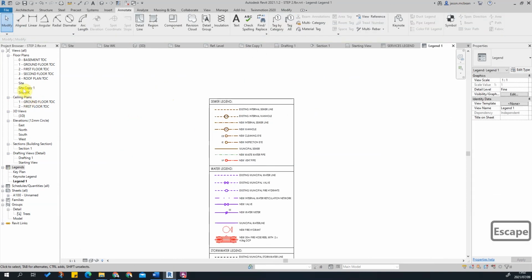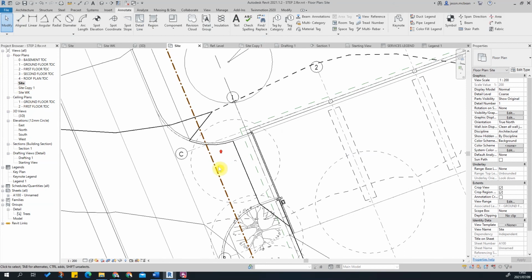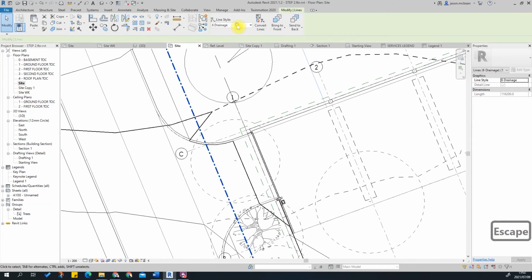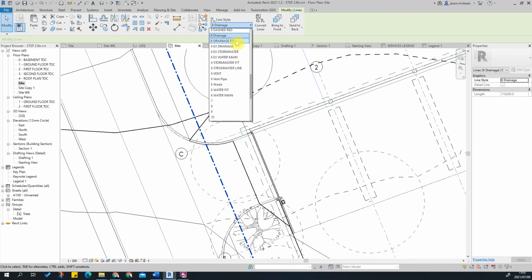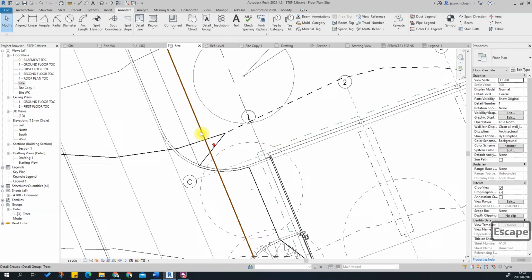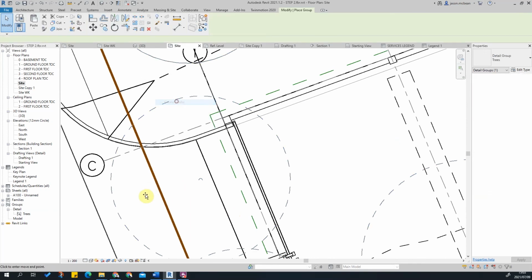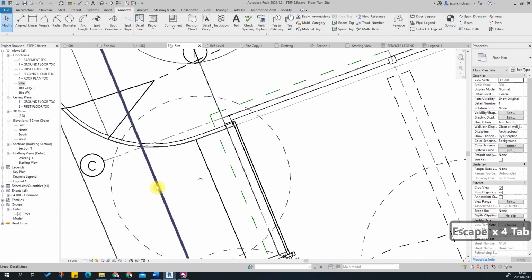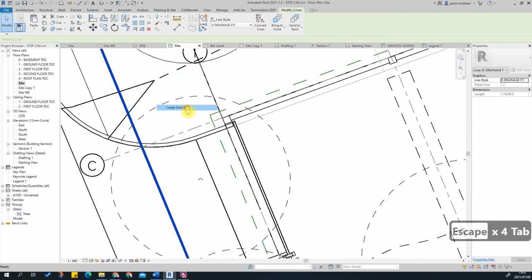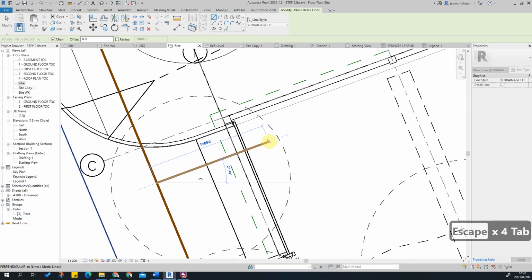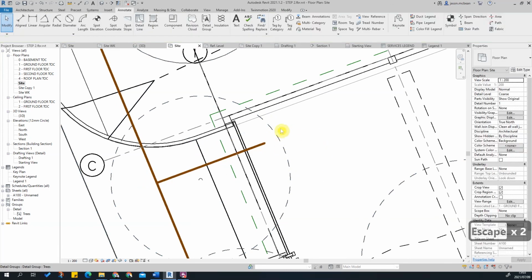Okay, so let's just go back to my site now. So now that should be existing, so that's drainage fit, because this is an existing sewer. Okay, right click, create similar. This will also come, sorry, just tab, yeah, create similar. Now it's going to come into our site, and there's going to be a manhole here.